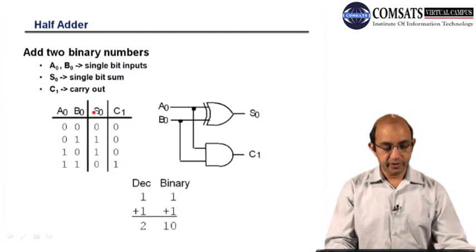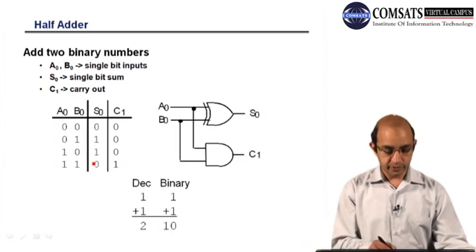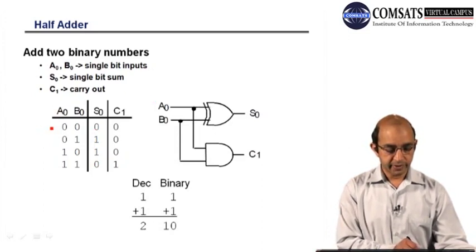If I have to draw the circuitry, because up till now we know the design and analysis, we have to design this circuit by using this truth table. We have 2 inputs, 2 bits. This is the sum output, this is the carry output. If I focus on S, I have two ones. So let me write down the terms: this is M0, M1, M2 and M3.